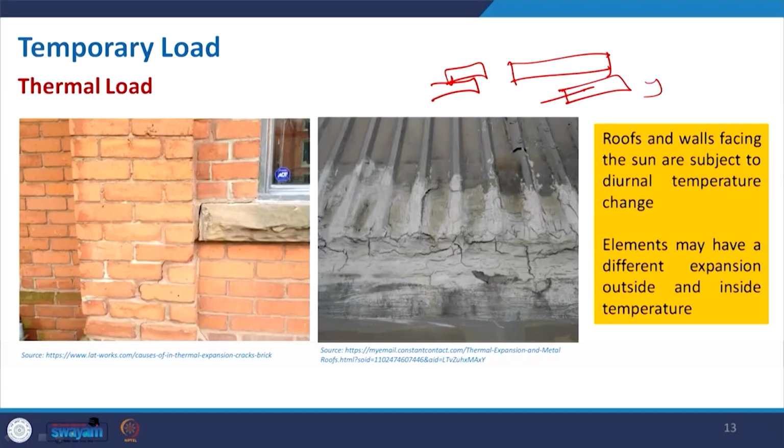So, whenever we have different kinds of materials, for example, here bricks and mortar, two different materials expand differently with a temperature difference, and it will develop cracks.